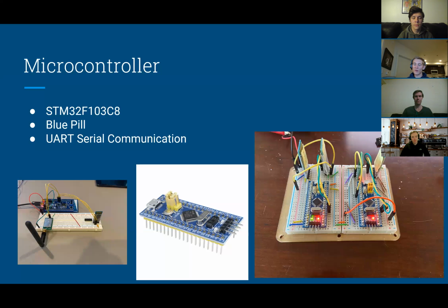Ultimately, we decided to go with the STM32F1 family of microcontrollers. This specific board that we used is known as the STM32 Blue Pill. And we decided to go with it as it met all of the requirements that we needed for the UART serial communication, as well as a nice compact form factor.